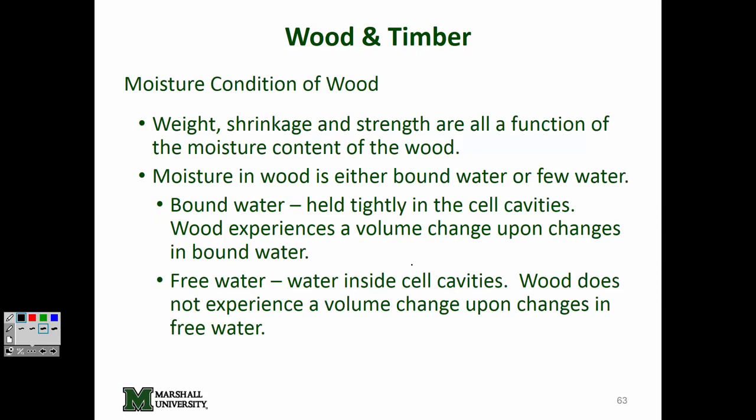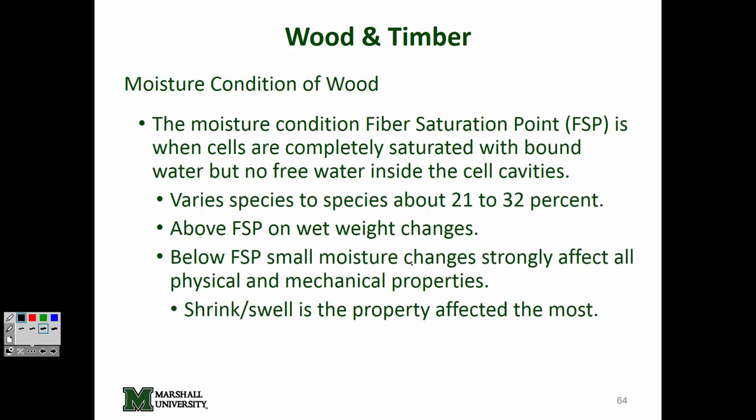Moisture content is critical when you're dealing with timber and lumber. You'll get shrinking and swelling, very similar to what we had with the concrete and having free water and all that kind of good stuff. We've got the same concept in the timber industry. We've got bound water and we've got free water. Depending on where the water content is in relationship to the fiber saturation point, tells us whether we're going to have shrinking or swelling at all.